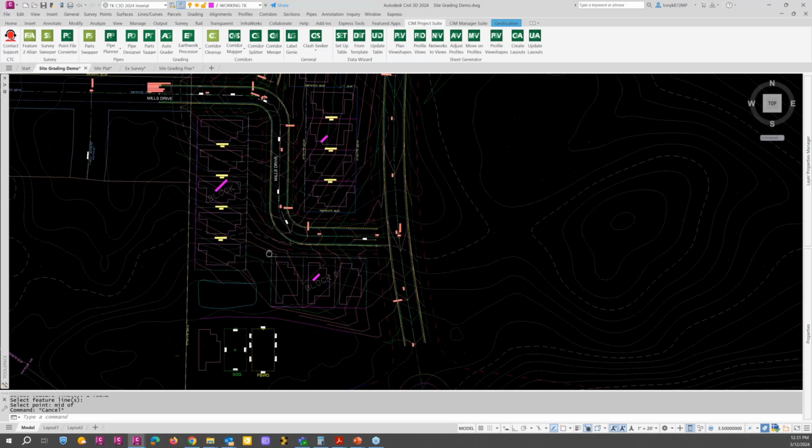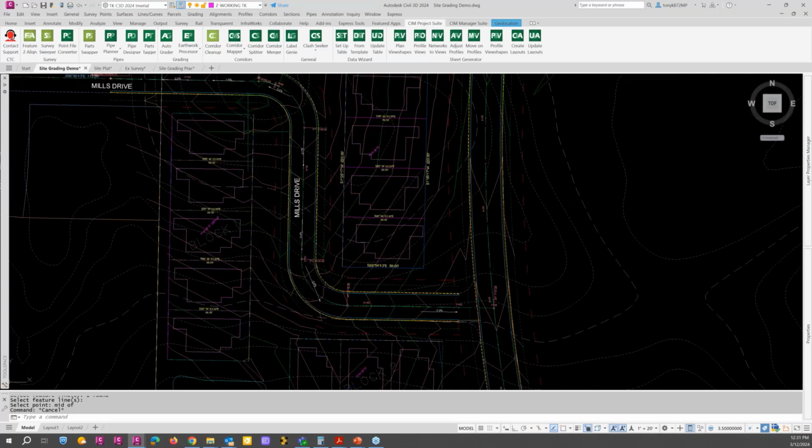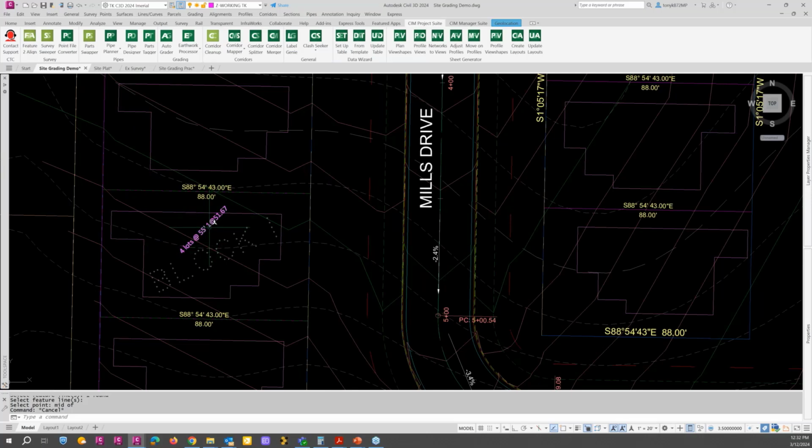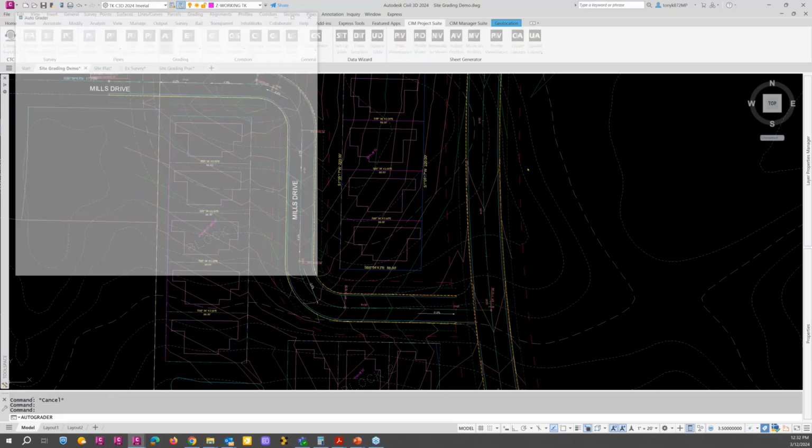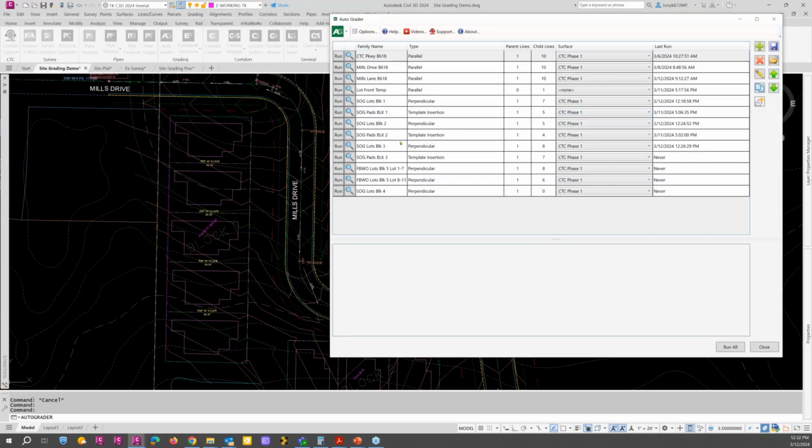Okay. So to do that, I just came through here and I picked the midpoint. And then I told it where it starts right here, because this is the oddball one. As I noted right here, 4 at 55 and 1 at 51.67. So I picked the midpoint and then I just went with my stationing every 55 from there. So that's where that first station number comes in. It's the midpoint between here. If it was 55, I could just type half of 55, 27.5, I think. But I used the AutoCAD commands to pick it.